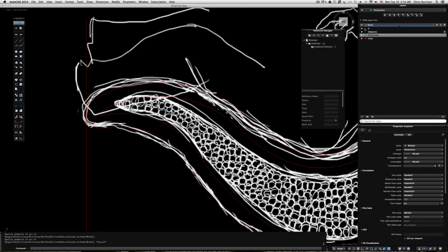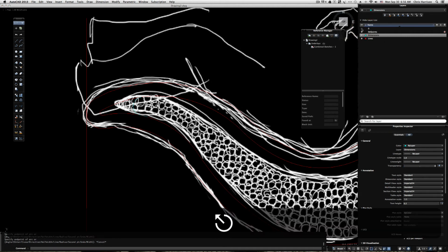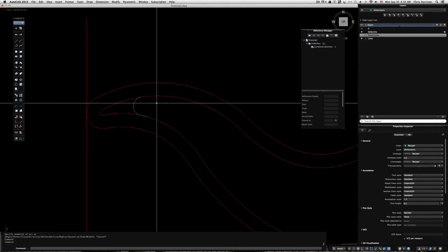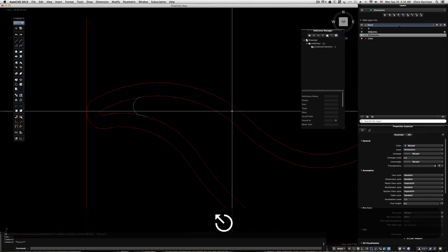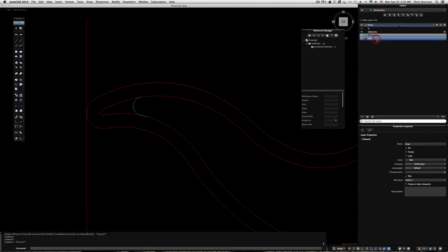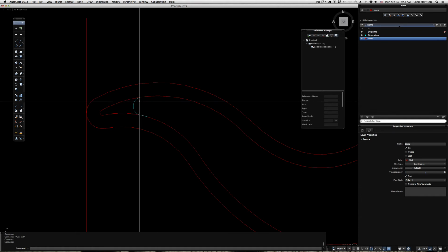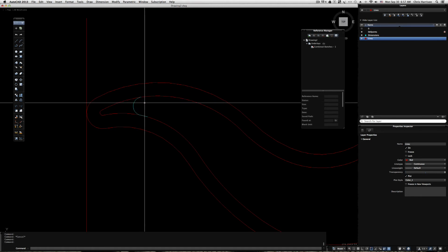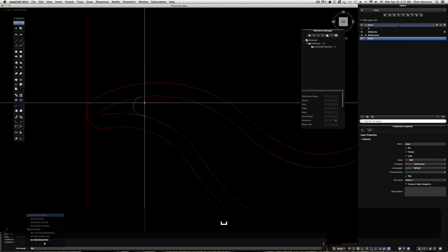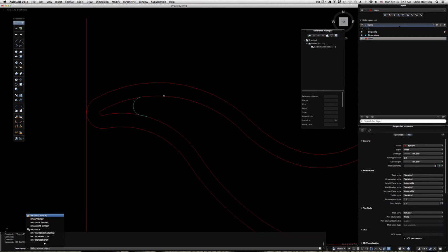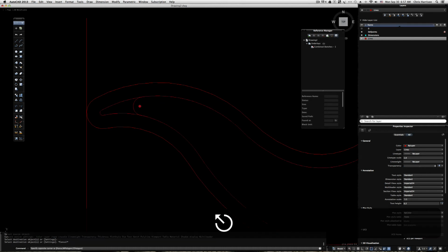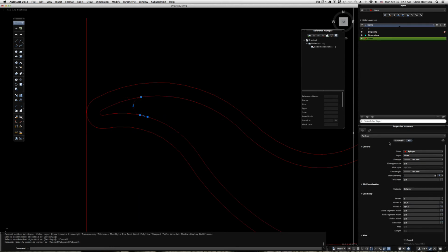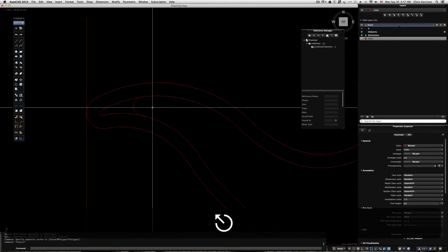Let me turn off the imagery that I've done that. Now I'm drawing, see, I'm drawing in my dimension layer, which is a no-no. I want to double click back on my lines layer. Now to change this, there's several different ways. The easy way for me is to do a match properties, and it's typing in MA, enter. I'm selecting the line that I want this to be, or the layer that I want it to be with the properties, and then simply selecting that, and you'll see it changes to red, and it's on the lines layer.